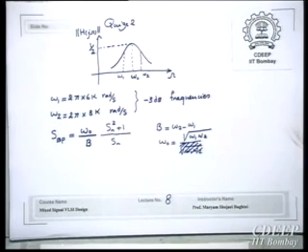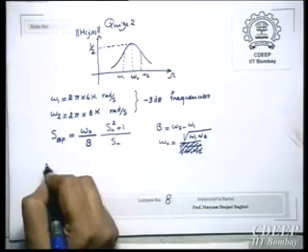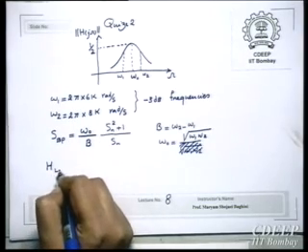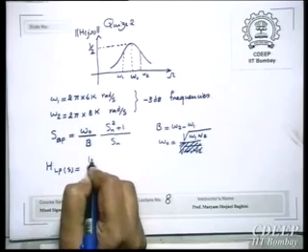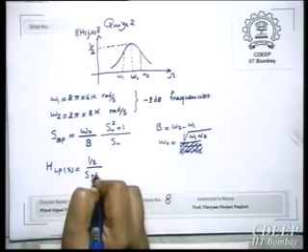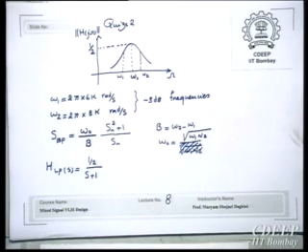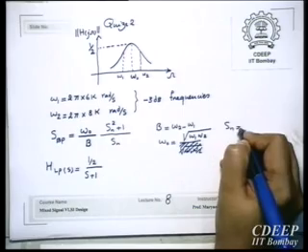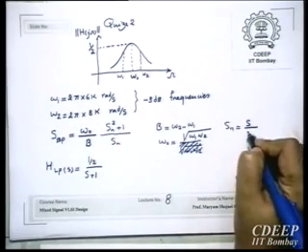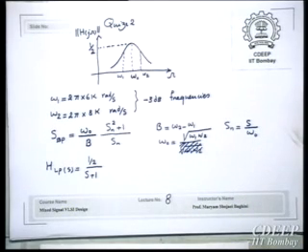And you consider we have a simple low pass filter with this simple relation. Therefore, it's very simple. Just convert this low pass to a band pass, which will have this characteristic using this relation. And Sn is normalized frequency, so it will be S upon omega. And just realize the filter and get values.